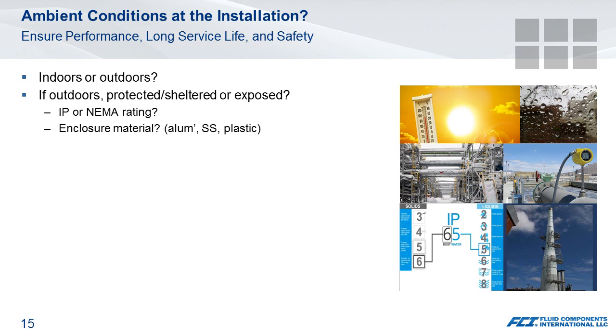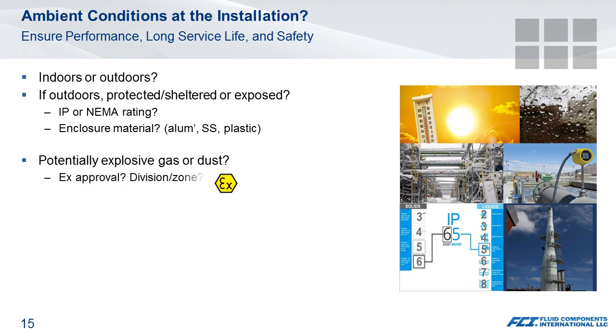The standards vary by region: ATEX in Europe, FM in the US, CSA or FMC in Canada, or IEC for the rest of the world are just examples. If you're specifying a thermal flow meter that's going on a skid or being exported, be sure the explosion-proof rating meets the destination country's requirements.